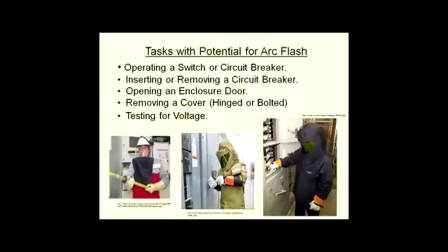Inserting or removing a circuit breaker or a fuse: you can see this gentleman right here, he is operating or replacing the fuses or circuit breakers. So that can cause an arc flash. Opening or closing an enclosure door. Operating the enclosure door, mostly opening.